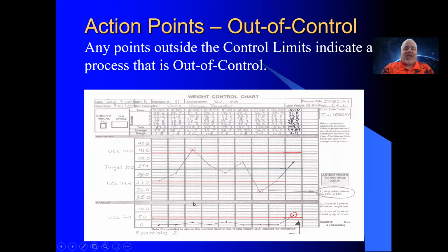This would have been a bad day to have 3 samples on the same day, the same line, out of control. But here you can see it was out of control because we're getting overfill. We're giving product away. Here it was out of control because it's under, and possibly a MAV violation.